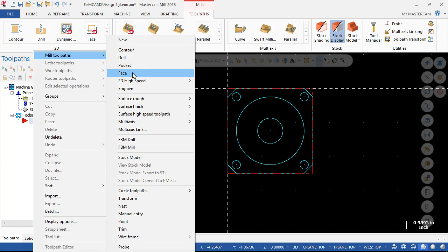All right, so our first operation is to establish our Z face. Occasionally stock will be right on size and it will have a nice surface finish, but 99% of the time we're going to make a facing operation to get rid of the gouges, the butter coat, the score marks, the manufacturer ink on the surface, and even adhesives and stuff gets included into that.